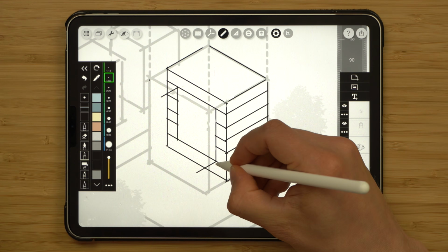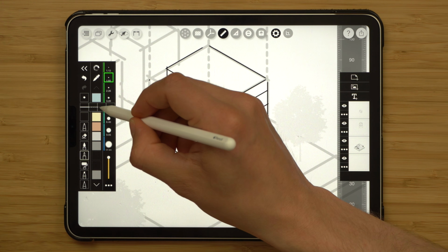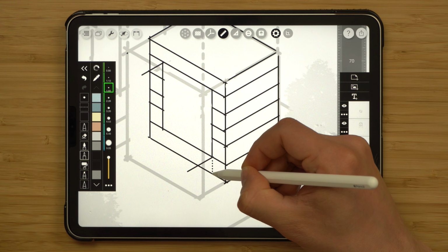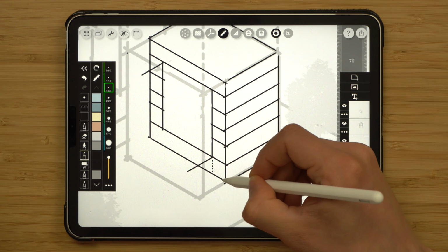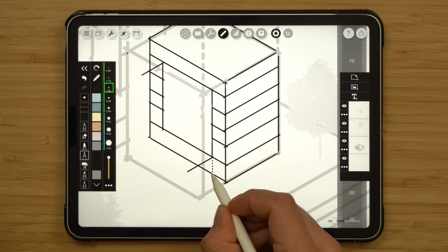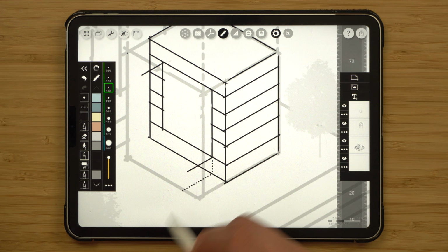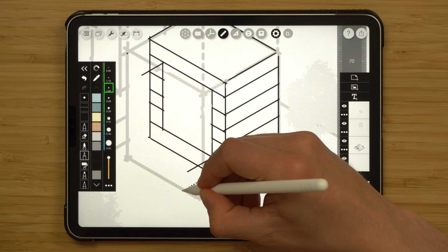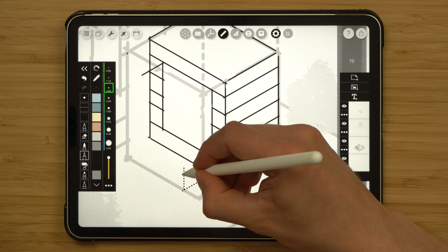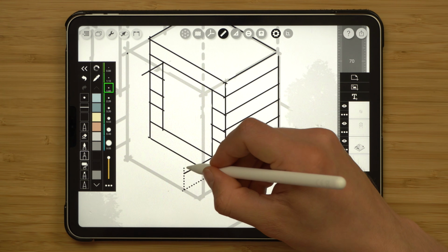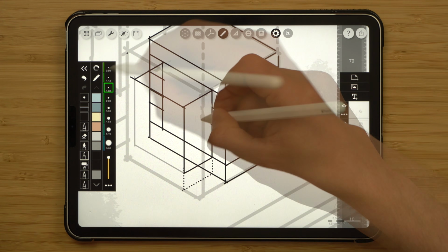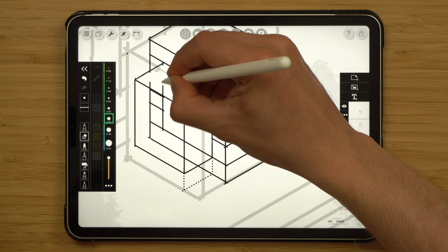So for that, what I can do is turn on the dotted line and project this line over here down to reach the bottom of that line here, and we know that the line at the bottom is coplanar with the base cube volume. So now we can pull it towards the edge, and once again, because this surface is coplanar with where we want the box to end, we pull it up, and this is the intersection point, literally where this box would end. And now we know for sure how much that extrusion needs to go forward. And again, just to make things clear, erase the edges.